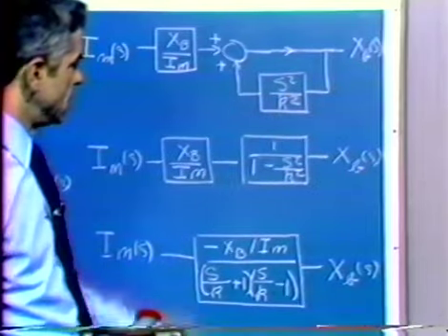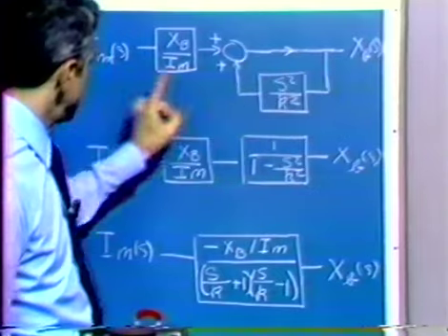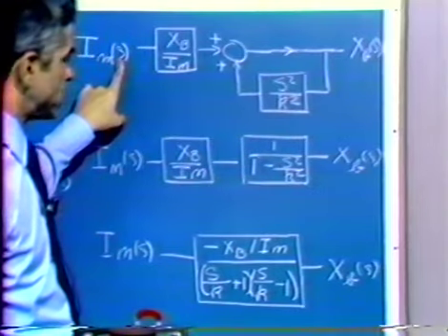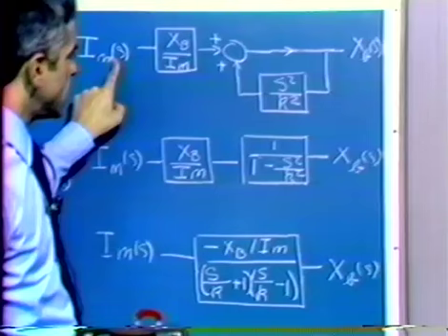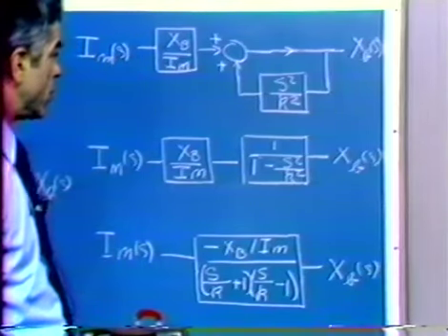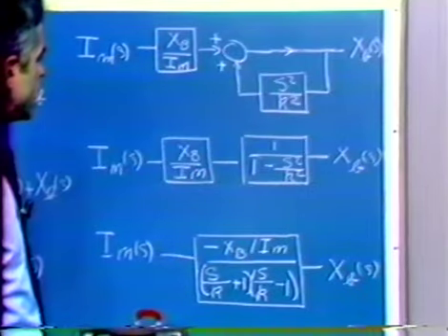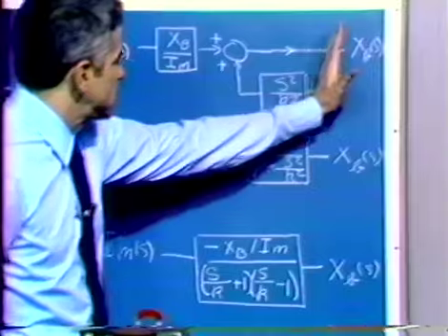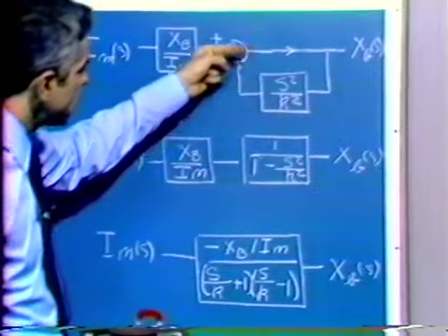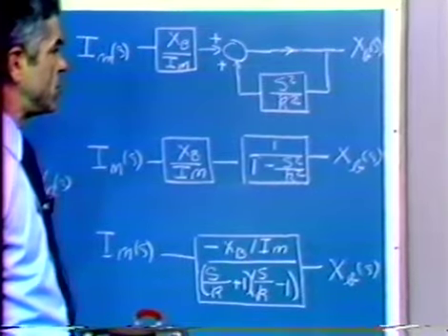So we get a little local loop in our block diagram that relates ball position to magnet current. This is the piece that we'd like to get. We will then make magnet current a function of ball position with an overall loop. We can simplify this block diagram a little bit, collapse this loop, and when we do that, we get the forward path over 1 minus the loop transmission.